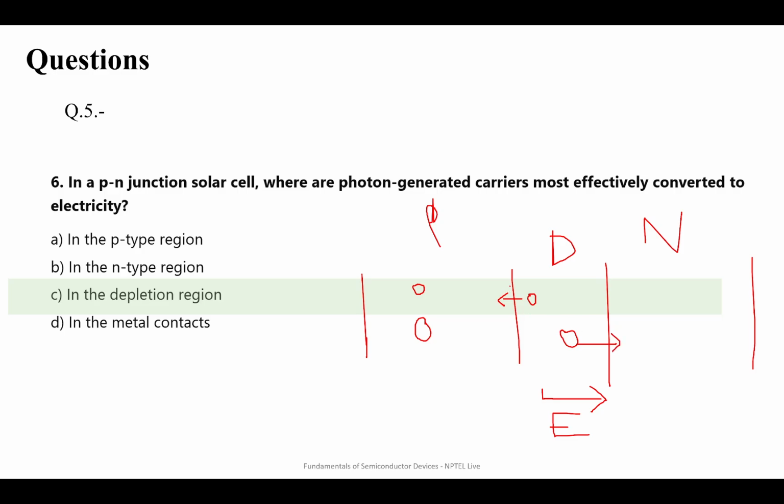And when it goes here, there's a diffusion length involved. This is called the diffusion length. When the electron is traveling through here, it is going to diffuse in the p-type region, right? Yes, sir. But there's a diffusion length after which it will get lost. So if I make my p-type region shorter than the diffusion length, then it will cross to this edge and get collected here.